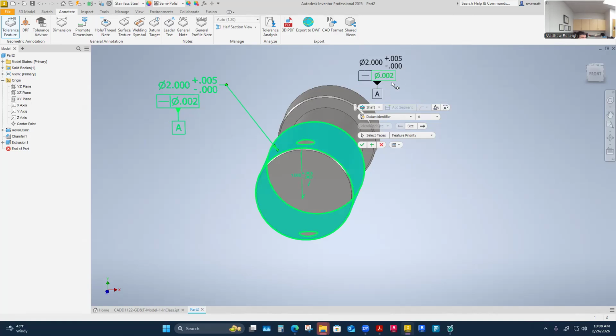If I change this to straightness, it will allow me. That's interesting. For cylindricity, its default doesn't seem to allow a diameter. It seems like it wants to specify surface, which is the intuitive nature of Inventor. But sometimes I have to say, well, cylindricity is definitely my form control, and I feel like I should have a diameter sign, but maybe not. Maybe this is an error on my other drawing. Google Gemini says it's the radial distance between two cylinders, so it's not a diameter, and not an extension of a smaller or larger cylinder. That makes sense, right?